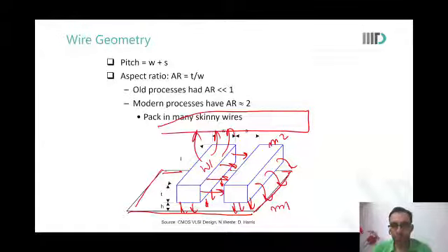How is this M1 different from wire 1? They are different metal layers, no? We saw the dual Damascene process. What were we doing? We were making one metal layer, then we made vias and the second metal layer, then we made vias and the third metal layer. So these are the metal layers. The lowest layer is metal 1, then you have these wires in metal 2, then we have metal 3 up there. Okay, sir, got it.